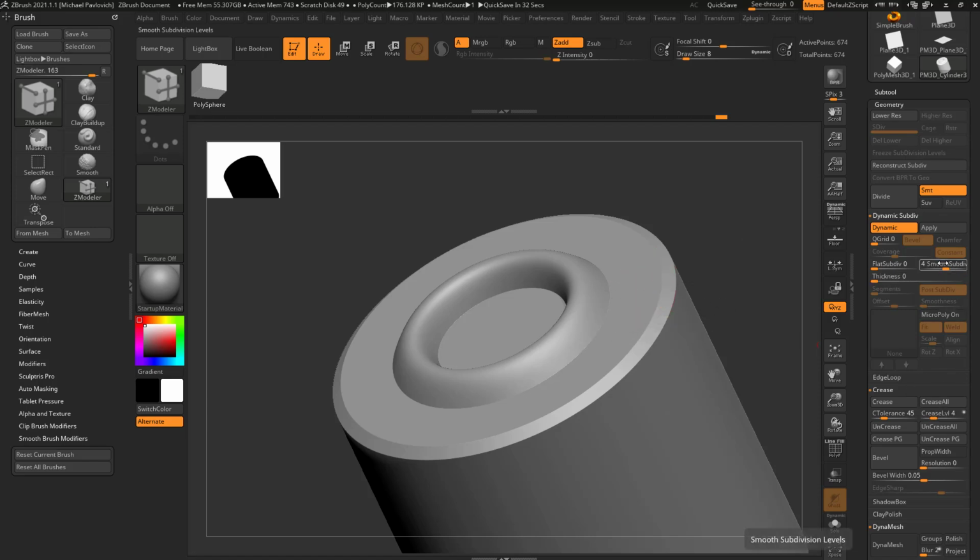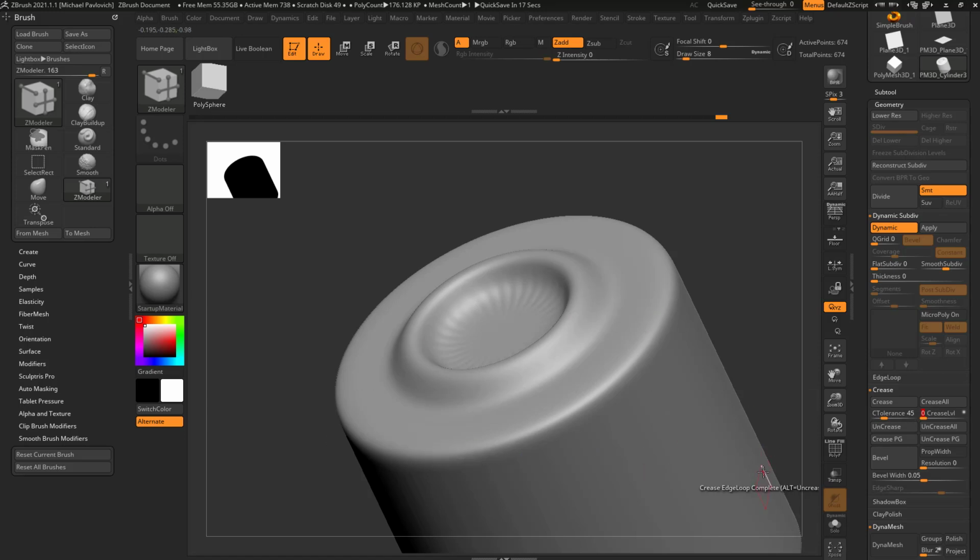As soon as the crease level gets below the smooth subdiv level, crease level of 3, you can see you get a little bit of a fall off. Crease level of 2, you're going to get even more fall off. Crease level of 1, even broader. And if we go down here to 0, it's like it was never creased at all. So again, if you want a very broad, soft fall off, a crease level of 1 and a smooth subdiv of 4, there's a lot of difference between those, and it's basically telling it stay creased for one subdivision and then uncrease for the rest.